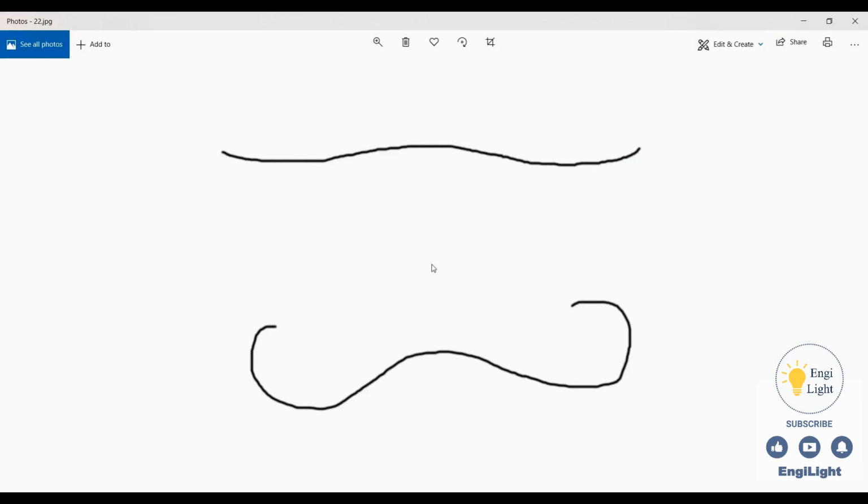Actually, the reason I brought up this image is to show you another way to create a spline. There's another spline tool called Style Spline. It gives us proper Bézier handles so we can shape the curve exactly the way we want. I placed this image here so we can import it into SolidWorks and put the two images side by side.